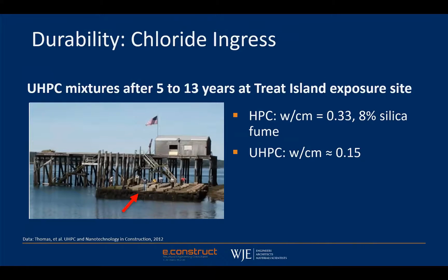So I also mentioned that the material had superior durability. Obviously in the Southeast, chloride-related corrosion is a prime concern. And so to talk about chloride-related corrosion, I wanted to show you some data from the Corps of Engineers exposure site at Treat Island, Maine.